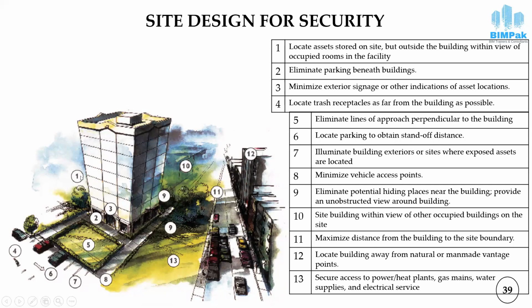The second factor is the parking. So eliminate parking beneath the building. While designing from a security point of view, you are not supposed to provide parking beneath these structures, because you have to provide sufficient standoff distance. So these are the parking areas, and there is sufficient green belt, which keeps the explosive material away from the target.